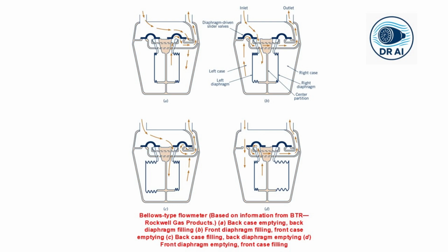The nutating disk meter handles a safe, relatively high pressure liquid, water. The bellows meter handles a dangerous low pressure gas, which is the natural gas. The gas meter must be sealed to prevent leaks, and the bellows mechanism allows this. Each device is perfectly designed for its specific job.